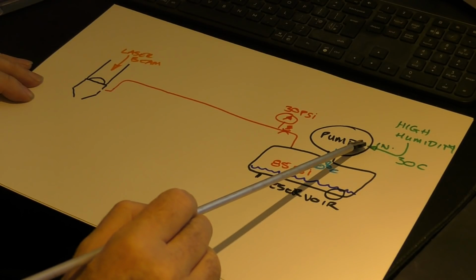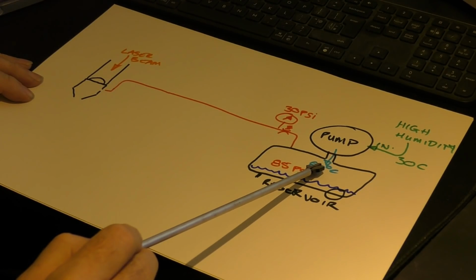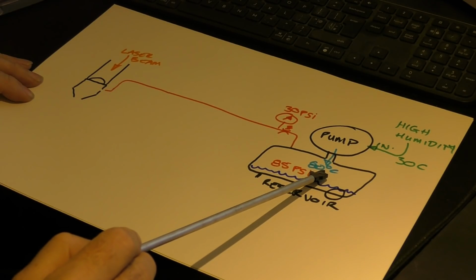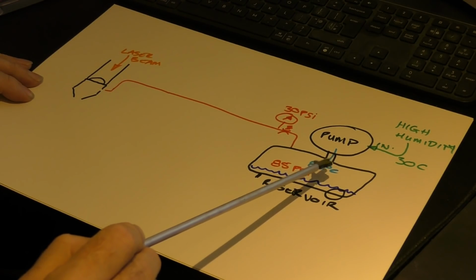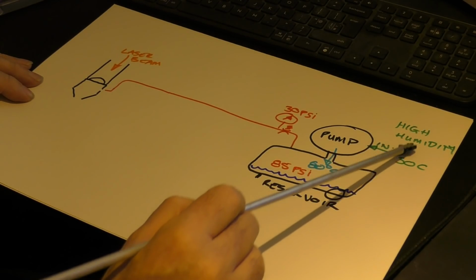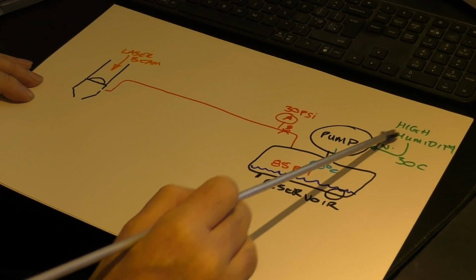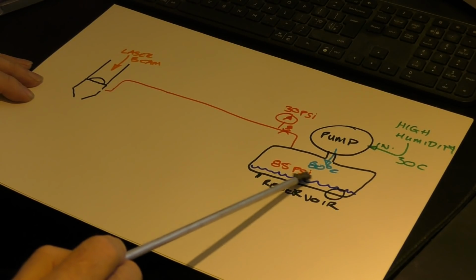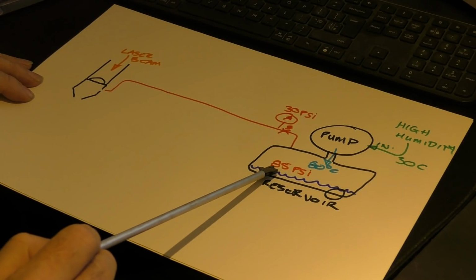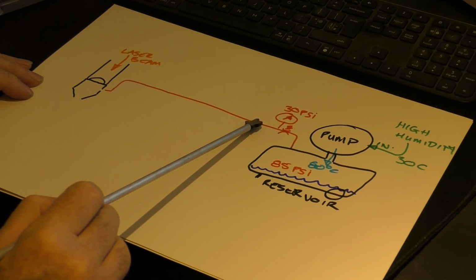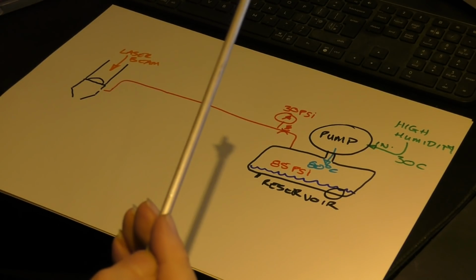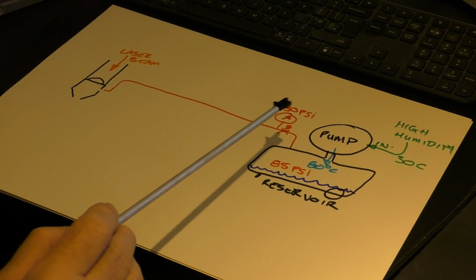So once you start the day and you start compressing air at 80 degrees C, remember, when air gets hot, it loves to suck in more water. And that air is sitting over a big puddle of water. So now you pumped in air at relative humidity for the atmosphere, but all of a sudden it becomes even more humid rich because it's hot. And then it flows down your system at, and some people are claiming 30 psi. And I was playing around with those sorts of numbers as well.